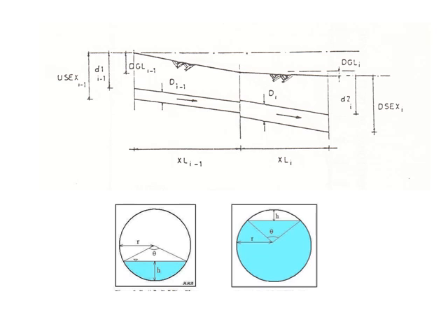For gravity pipes, you can see that water does not move in its direction due to differences in pressure, but due to differences in elevation, because water flows by gravity, and the section is not full of water. It is partially filled with water, as you can see in the two sections at the bottom of the graph, where the design variables differ a bit. In addition to pipe diameters, they have to do with the slope of the pipe and the excavation depths.